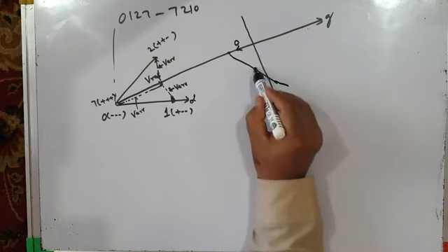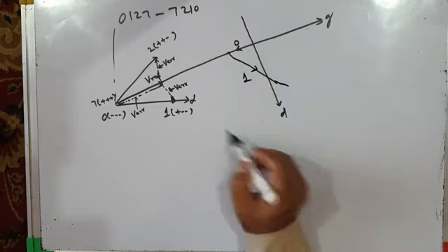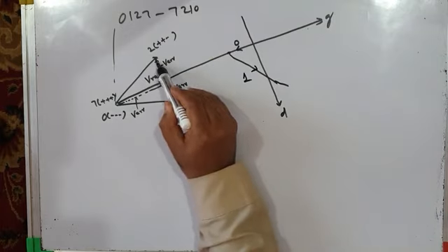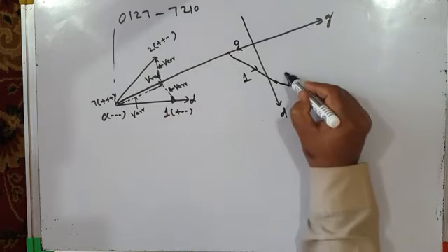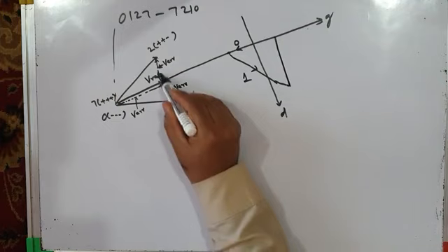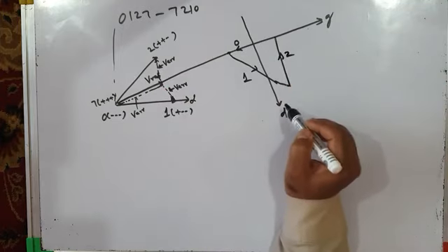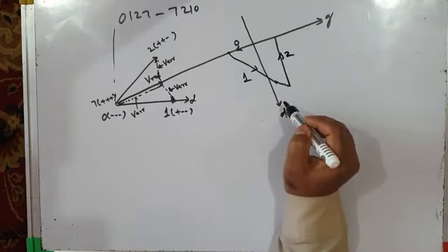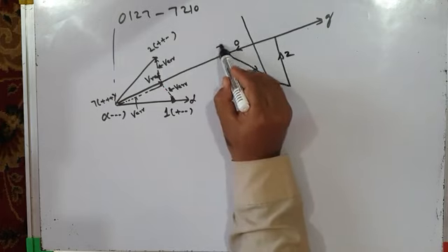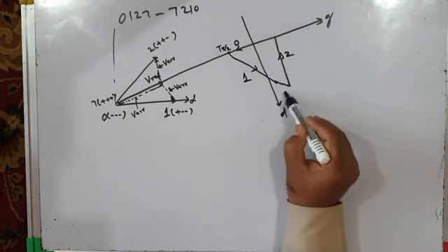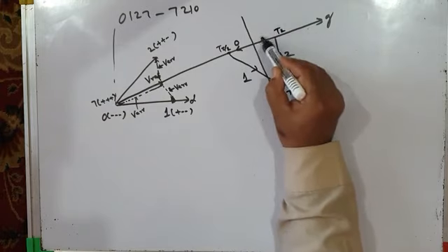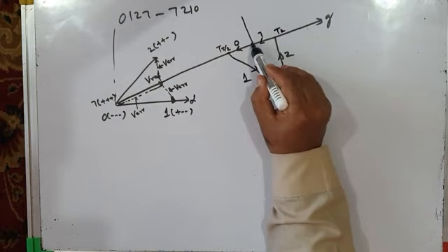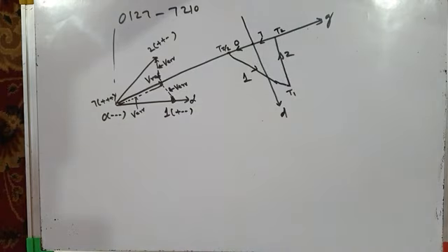Okay, so this is when active vector 1 is applied. And when active vector 2 is applied, and we have error voltage vector VR, when it is integrated, it will give us stator flux ripple like this, which is moving parallel to this when active vector 2 is applied. Null vector 0 is applied for time interval tz by 2, active vector 1 is applied for time interval t1, active vector 2 is applied for time interval t2, and then null vector 7 is again applied. So this completes the subcycle.